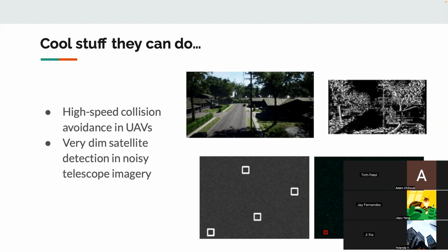What we did was train a spiking neural network with reinforcement learning, deep Q learning, with a simulator that we built. This was a simulation of the event-based sensor within the AirSim simulator. You can see it's a rough approximation of what an actual event-based sensor would see. We trained that, and ran through and did a lot of high-speed collision avoidance.